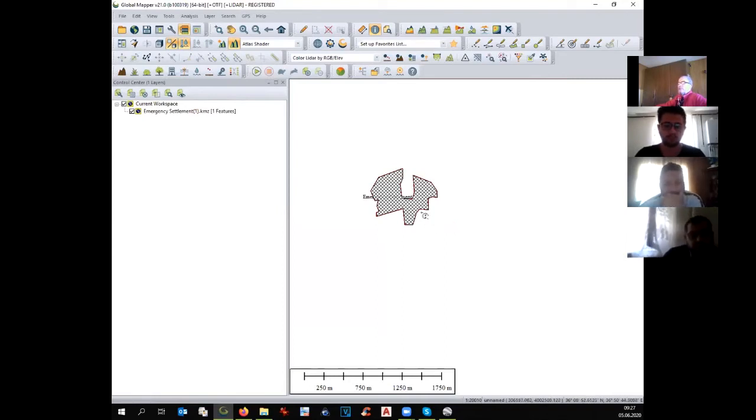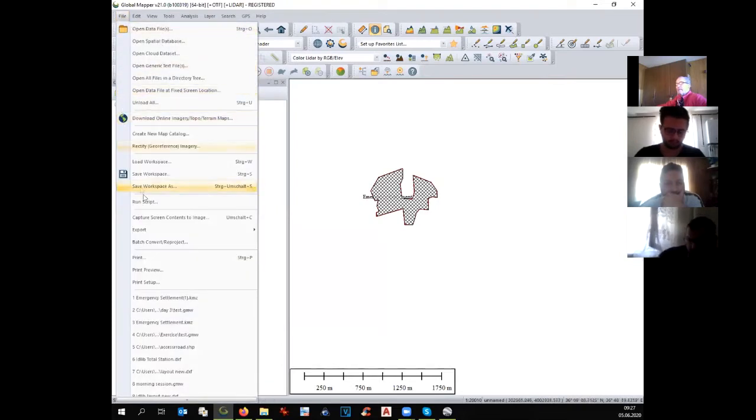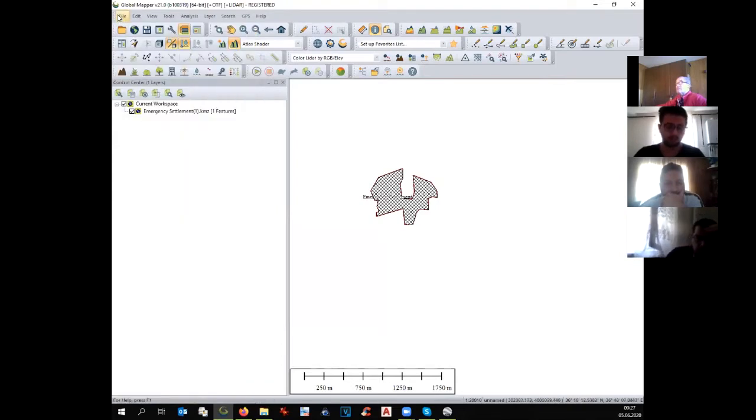And the way to do it, it's very simple. You go to File, oh no, sorry, I just forgot at the very beginning. You have to install your Global Mapper in a way that you are in metric projection. I spoke about that, but I repeat it because it's very important. Since we are going to work with AutoCAD at the end with the same area, we need metric projection. That's why everything we do from the very beginning must be in metric projection.